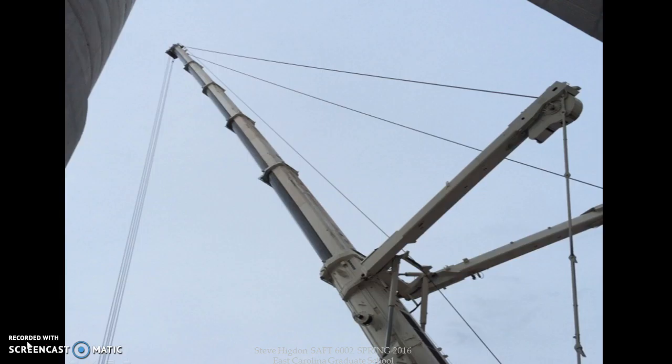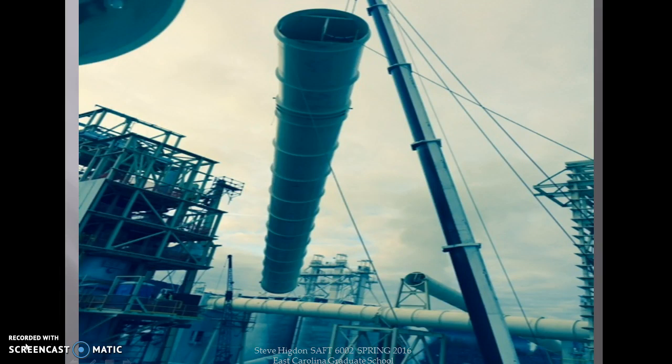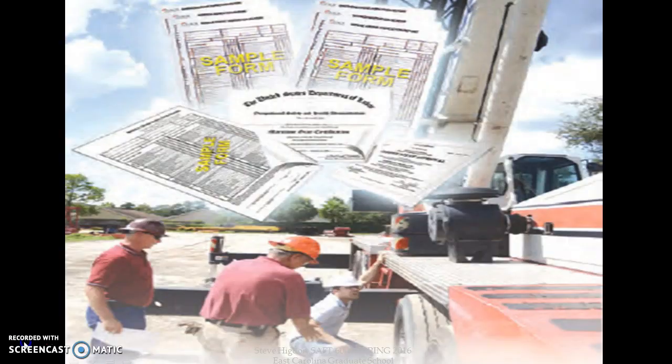This means the area in which the load and each component of the crane will be swinging. Cranes have gantries and masts that may hit something if you don't make sure the swing radius is clear. Loads must be controlled with tag lines to keep them from swinging into other objects or other pieces of equipment. It is very important that you control the load and make sure that no one is walking under the load or around the load.